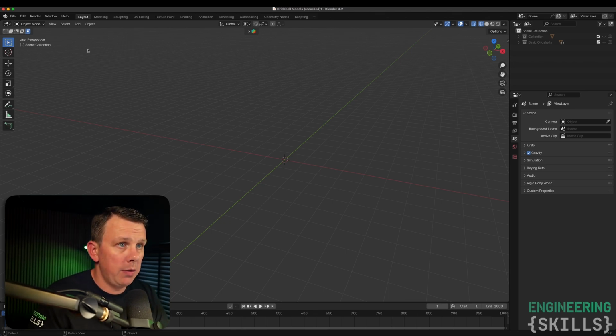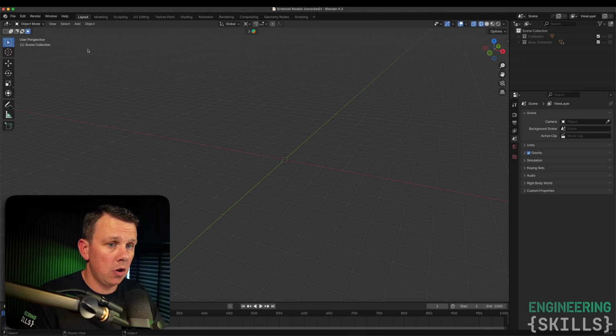So what we're going to do in this tutorial is focus on a relatively simple grid shell structure. Of course, all of the steps that we do in this tutorial you can apply to a more complex structure, but for the purposes of just demonstrating the workflow here, we're just going to keep it relatively simple. So I'm going to generate a grid shell that is 10 meters by 10 meters on a 1 meter grid. That's going to be our flat cutting pattern, as it's known.